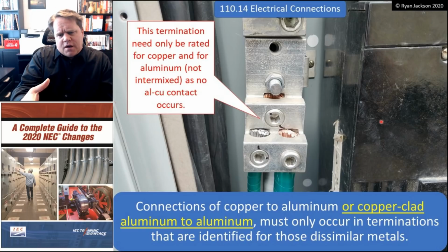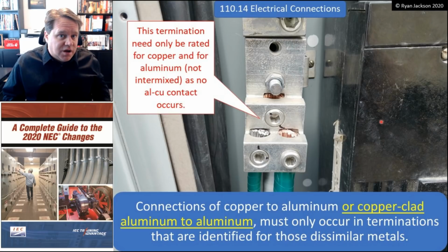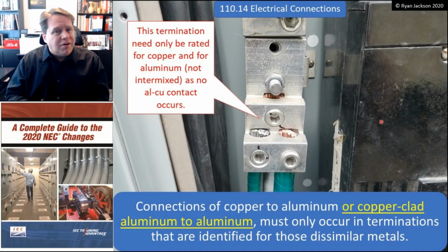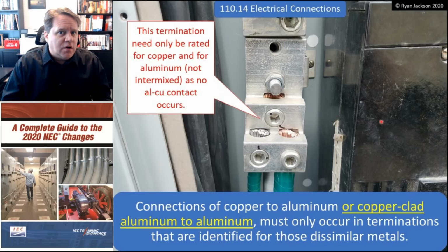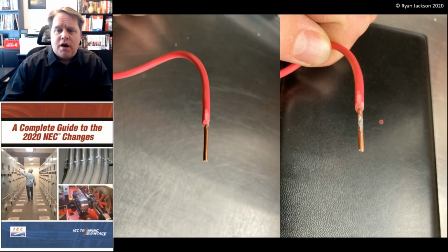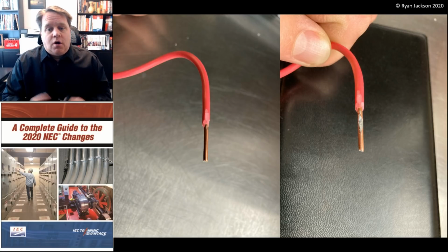But I want to get back to the change here, and that is copper-clad aluminum. Copper-clad aluminum has actually been around for an extremely long time, but it kind of picked up in popularity in the 70s. And then it more or less died off. The idea of copper-clad aluminum is exactly what it sounds like. It's an aluminum wire with a copper perimeter around it. In fact, here's a photograph, same conductor, and we just kind of scrape the outer surface with our knife. You can see that it appears to be a copper conductor, but underneath it's actually an aluminum conductor with copper metallurgically bound around the aluminum.